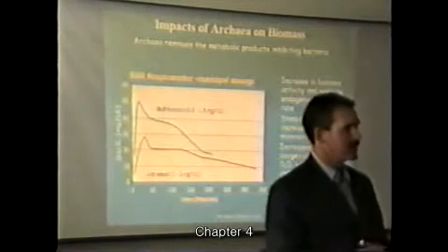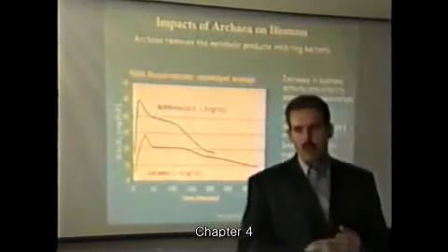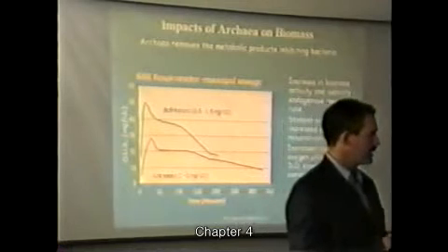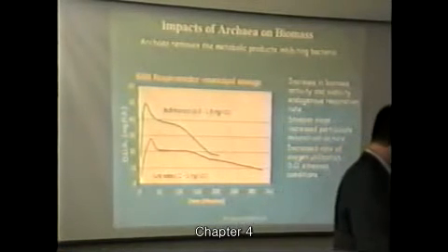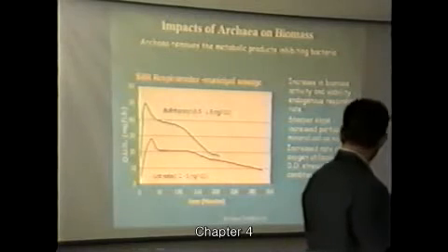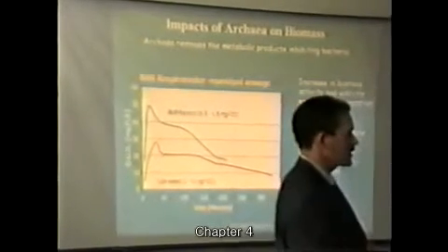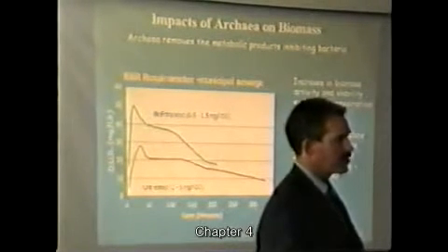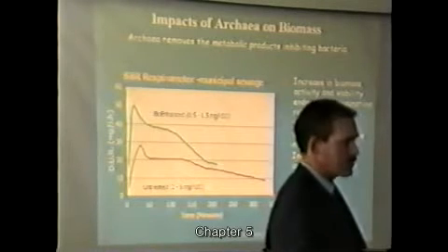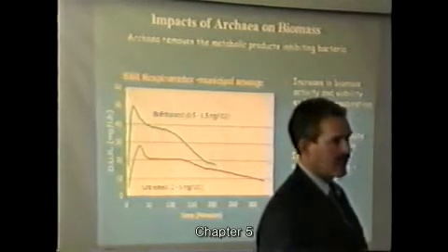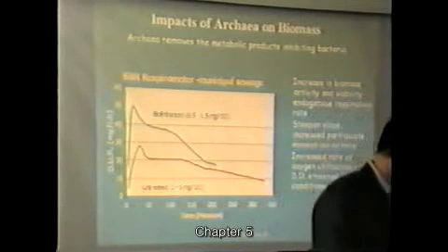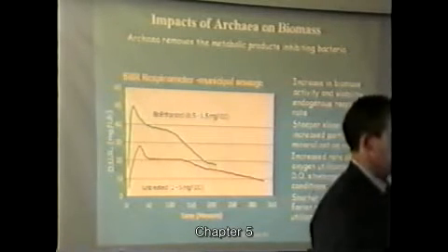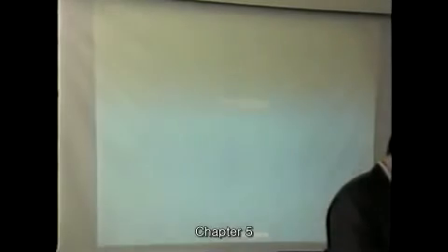The interesting thing which I forgot to mention is the bottom curve, the control curve, was done at a dissolved oxygen concentration of between 2 and 5 milligrams per liter, which is typical of a system. Ours was operated between 0.5 and 1.5, which we would typically consider as being stressed. Anything under 2 milligrams per liter dissolved oxygen, you have a problem, especially with nitrification. Okay, and then the shorter cycle time, so we can do the same job in a smaller reactor.